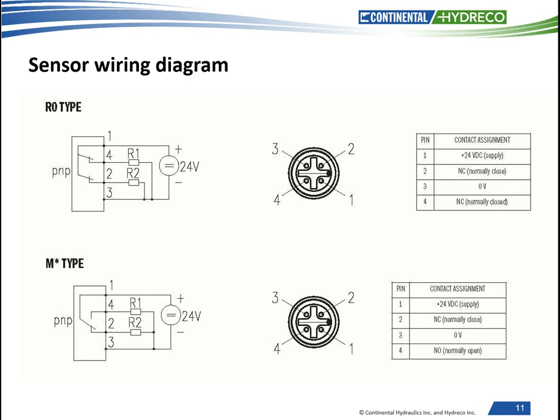When in the neutral position, both outputs will show high. When one solenoid is actuated and moves the spool, one of those two signals will then drop low. This change in output status is used by the control architecture for two important things. One, it alerts the system that the valve is no longer in the neutral position, and two, based on which output has changed state, it indicates the direction that the valve is operating in.